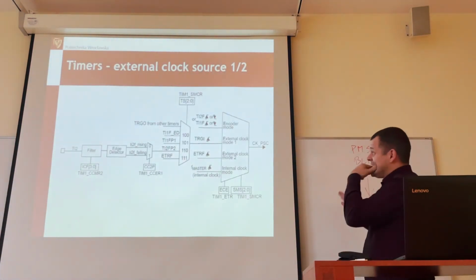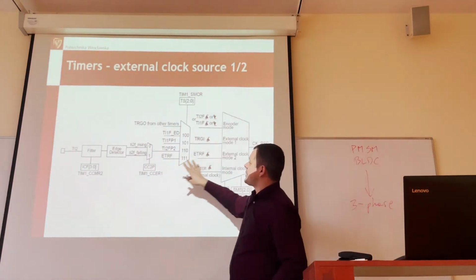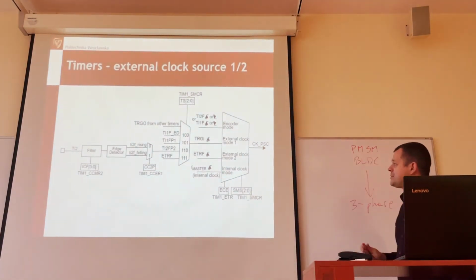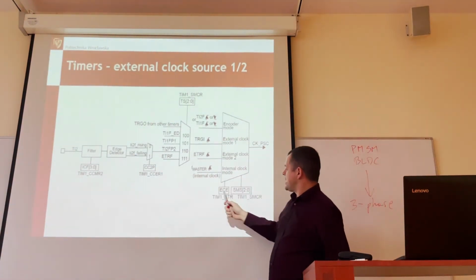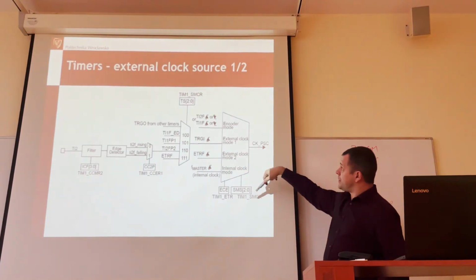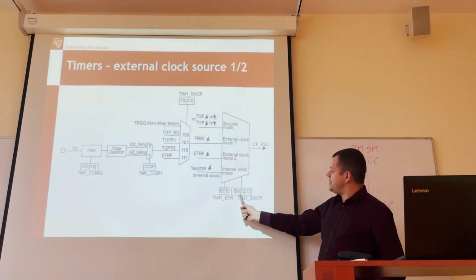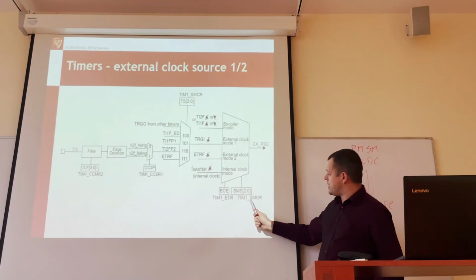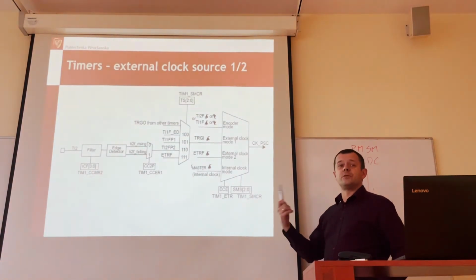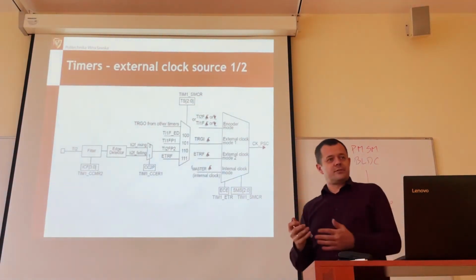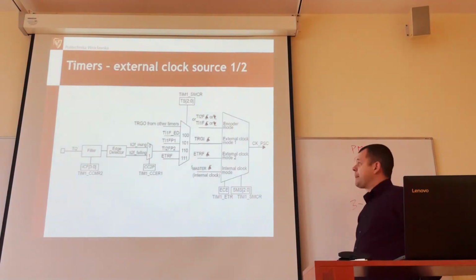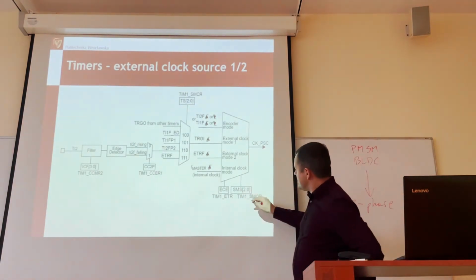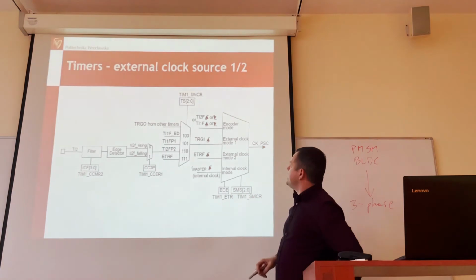Why? Because take a look. This is the circuit just for connecting what is connected to CK/PSK. And normally the default one is this multiplexer. Take a look at this chart. We can read directly which register and which bits in the register, because this is the TIM1 register SMCR. So if you want to modify it in software, you just open such a chart and you can read from it which register, which bits in the register modify the particular multiplexer. So these bits change the inputs.